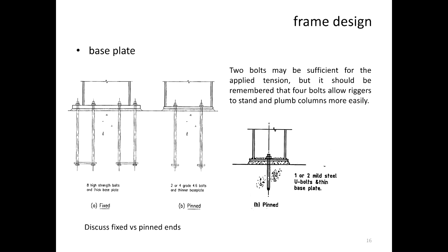Unfortunately, you will not be able to see this because they have already finished all the structure, so you will not be seeing that. But you will see definitely the grout. So that underneath is the non-shrink grout. So that grout is put under the base plate and it doesn't shrink at all. Okay? So that's what a fixed moment is, a fixed base.